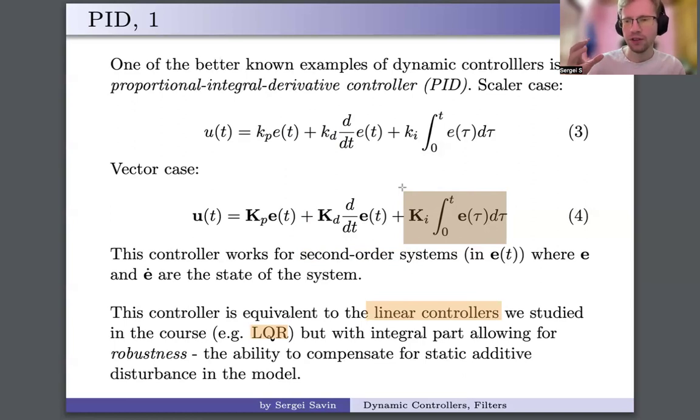If your model missed a little bit of the dynamics, let's say the gravity was not computed correctly, and it was not compensated correctly. So your plant, instead of keeping the, let's say your robot has an arm, right? It sits like this. But because the gravity was not compensated correctly, it sags a little bit. So the arm, instead of being like this, it's kind of like this, right? The integral term computes this error. Say, okay, it should be here, but it is here.